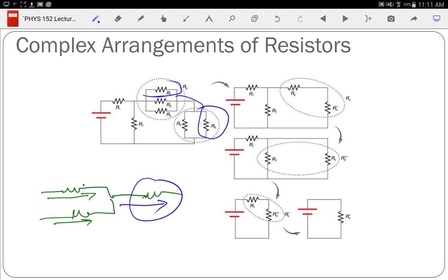So you take these and break them up. As they've done, you have those 3 that are in parallel, so you combine them and replace them with one equivalent resistor. You have the 2 that are in parallel. You combine them, replace them with one equivalent resistor. And then when you reanalyze, you see, hey, these 2 are now in series. So then you combine those 2 in series. Why are R1 and R7 not in series here?